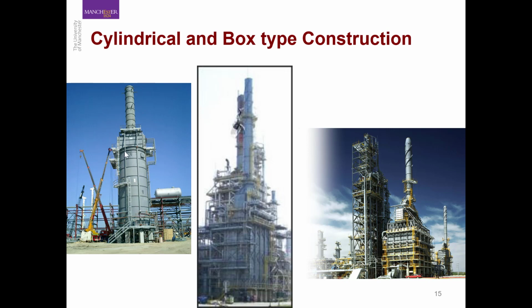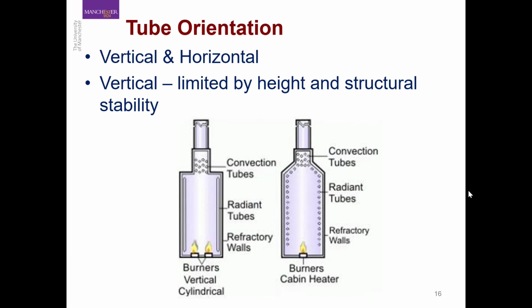So you have to bring this whole unit as one. And as you can imagine, the logistics of moving this whole thing from the construction site to the plant site will be a nightmare, because you have to close the roads, you have to worry about the weight limits of the bridges and all these things. So that is why, in some cases, we prefer to use box furnaces, because they are much easier to construct.